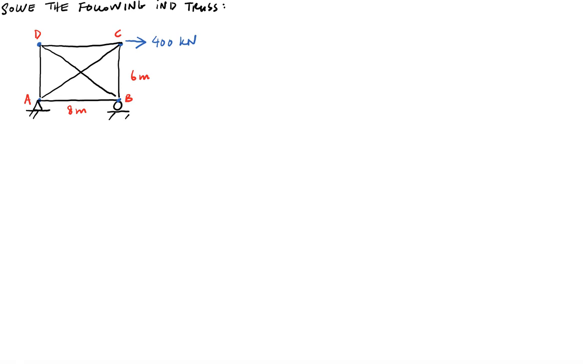Okay, today I am going to show you how to solve for indeterminate truss using force method. So the first step, similar to the one before, is to calculate the degree of indeterminacy. Okay, so the degree of indeterminacy for trusses, if you can remember, it's m plus r minus 2j.